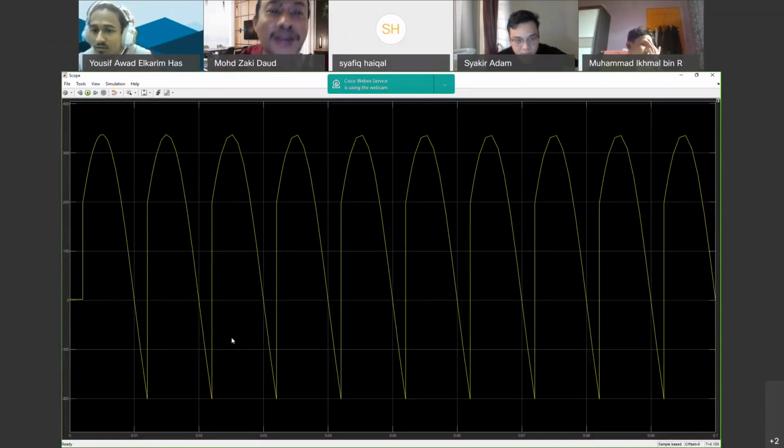And then what you should do, you should put the freewheeling diode. Alright? Oh, yeah, I have to add it too. Yes. And then we remove this, and we can see that the output, you eliminate those things. Okay, that means you have to show that there is an evolution with your results. The result you first without freewheeling diode, and then you put freewheeling diode.